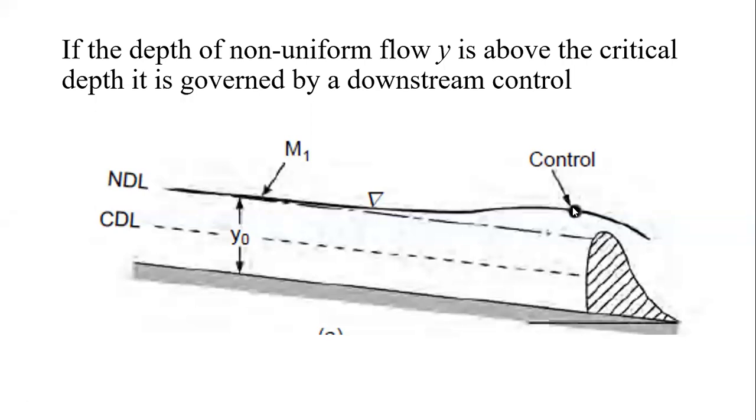In the upstream side, from this point the water surface profile is a back water surface profile, whereas to the downstream end of this control point there is a drop down water surface profile. So this is nothing but the control point which clearly indicates the change in the water surface profile. Just a minute, I would like to mute all the participants.